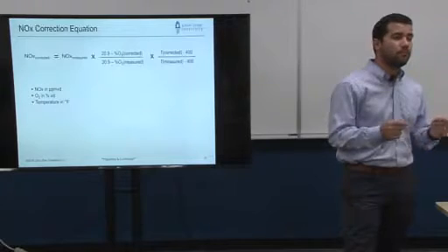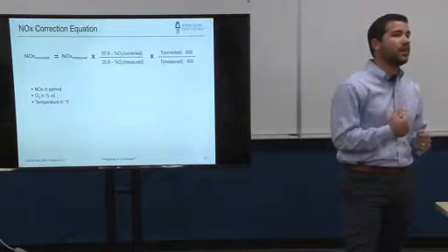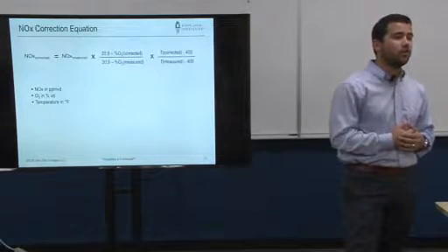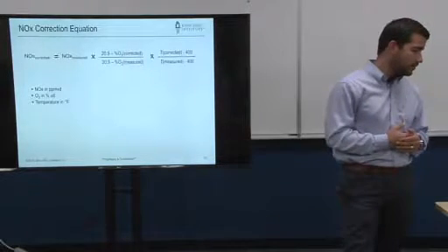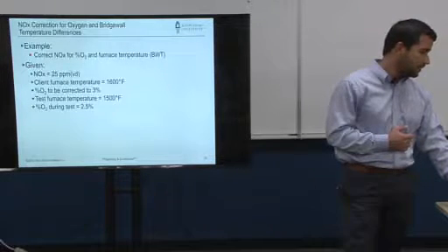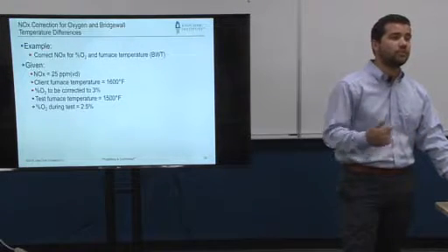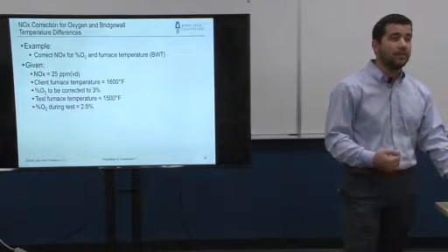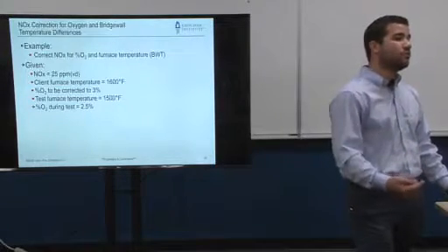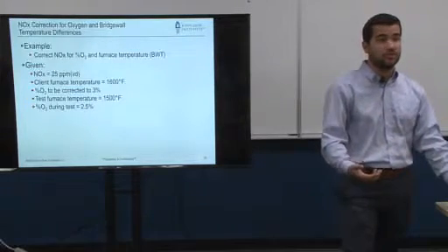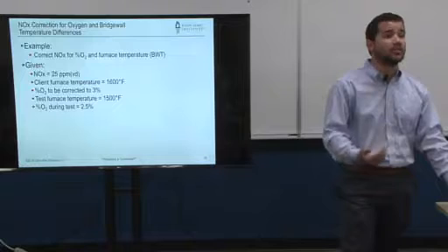And one big note about that is that it's not a predictive NOx. So I think in this particular case, if you take 25 ppm at 2.5% O2 and you correct it to 3% O2, you're going to get something like 25.5 ppm. That does not mean that the burner will produce 25 ppm when it's at 3% O2. This is not predictive. It's just a correction that you're applying.